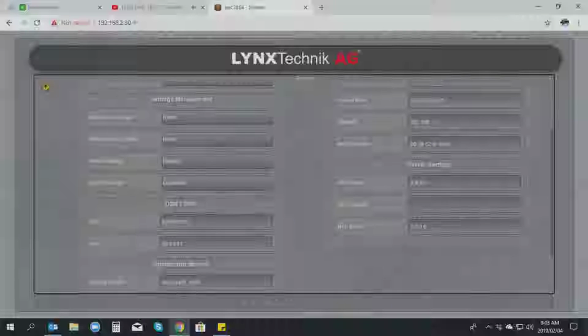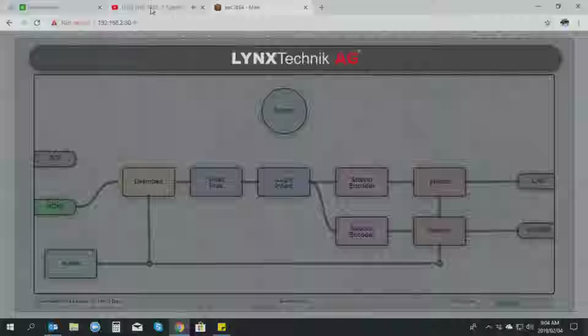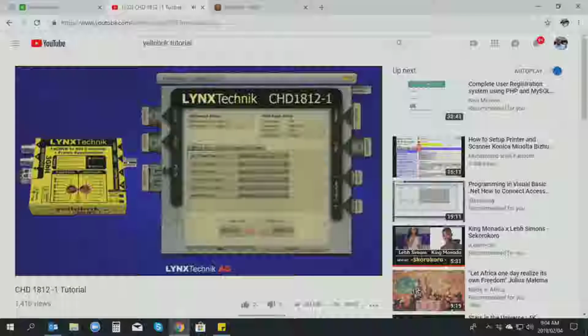the input into that standard or that frequency on the output. That's a particularly useful function in the US market, where there is no real delineation between 60 Hz and 59.94 Hz in HDMI, because it was originally developed as a consumer format for use with monitors, and monitors don't really care about that tiny little difference between 59.94 and 60 Hz. It's certainly not an issue for a monitor, but in a production environment it can be a real big problem. A little difference adds up and causes us all sorts of timing problems.